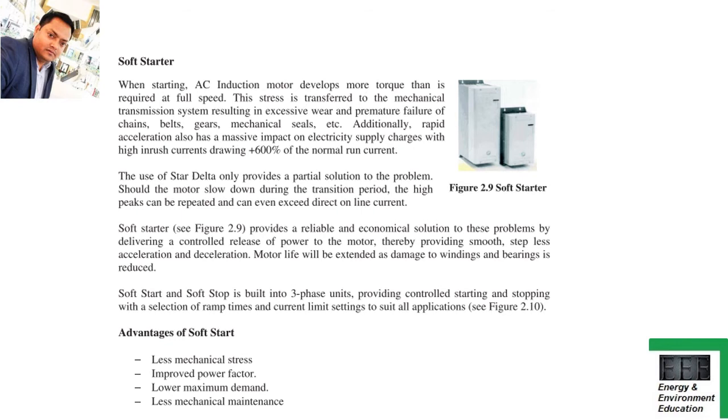And another important topic for you to understand is the soft starter. Why the soft starter is important, what are the advantages of the soft starter. If you see the soft starter advantages, it has less mechanical stress, improves the power factor, lower maximum demand and less mechanical maintenance. These are the four important advantages of the soft starter. So basically they may ask you what a soft starter is all about, why the soft starter is important, or the advantages of the soft starter.